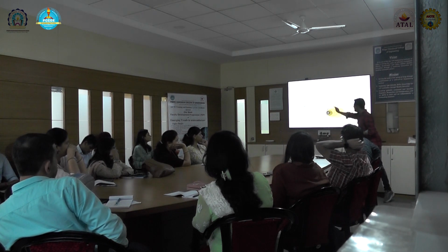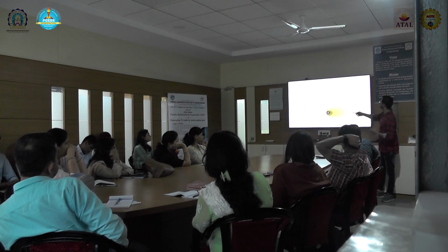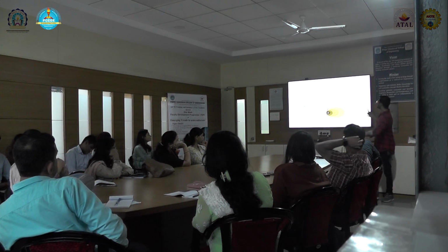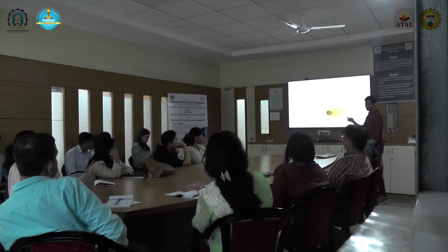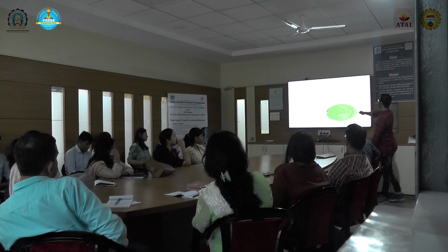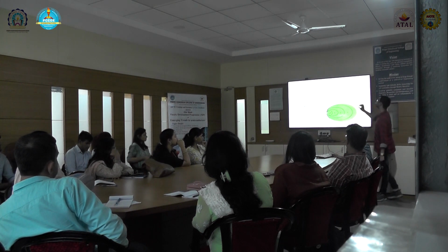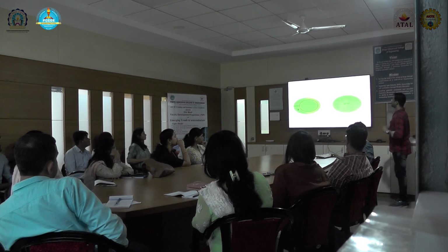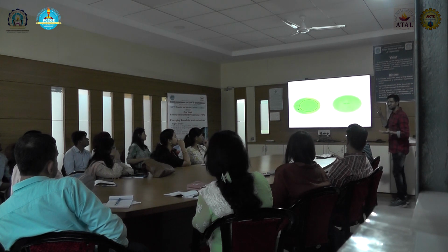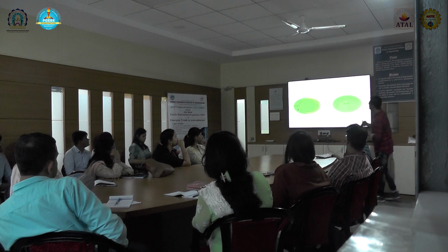So this is our complete design space, in which not all the combinations are legal. After adding constraints, it will get into some legal states. So now we don't have to cover this complete scenario. We will cover this much scenario only in formal. Okay. Now it's not like you can write n number of constraints, because writing constraints has an effect on formal.